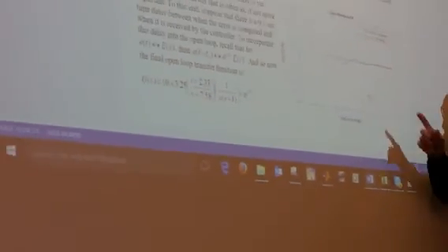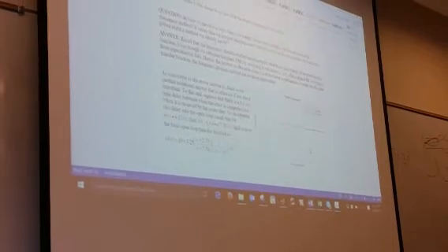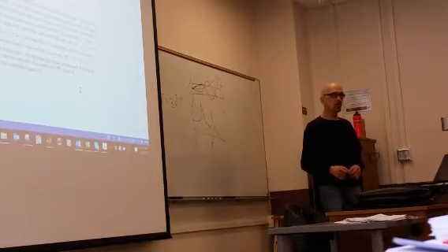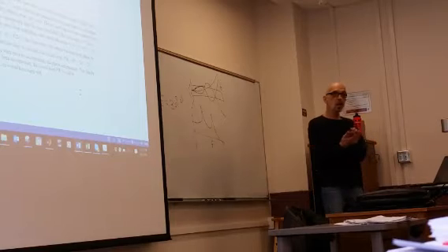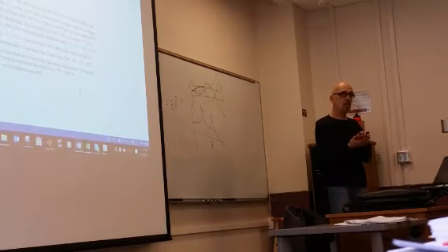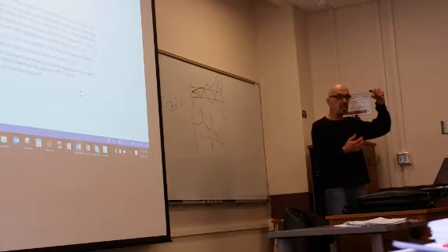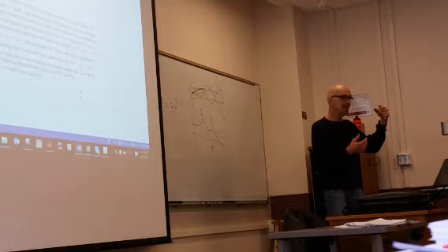So this is what happens when you have a time delay in there, and you cannot handle the root locus with time delay. Why? Because for the root locus, where you give it the open loop transfer function, you have to give the transfer function in terms of poles and zeros. e to the minus st, no, that's not a polynomial in s.